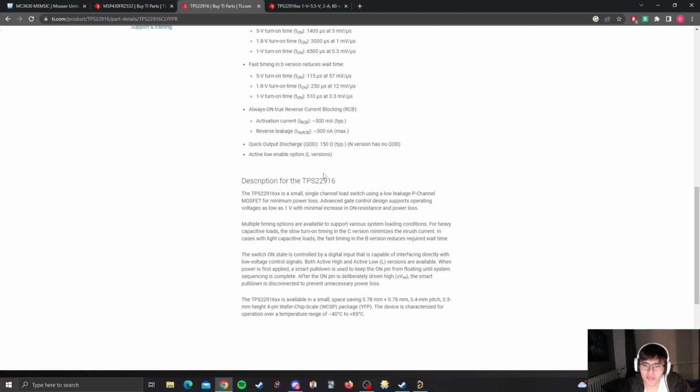Well, compared to a load switch, in this case, you do not have the benefits of it, such as inrush current control. They may have like a power good output or some thermal shutdown feature, something of that sort, which makes your circuit a bit more robust, and you could do a lot more things with it. You can still achieve the same effect with a FET, but you just have a bit more components onto it, which means your cost increases, your complexity increases, and as well the size of your circuit. So why put in any of that when a load switch can achieve just that? And this is why someone might use a load switch over just a simple FET.